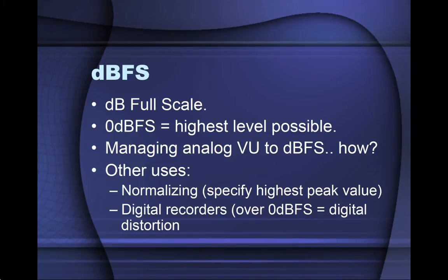Another way of looking at it is, okay, a 16-bit or 32-bit recorder, however many bits it is, 0 dBFS is filling up all of those bits. So if you're going from an A to D converter, the maximum input voltage in an analog sense equals 0 dBFS. It's the most that it can handle without overloading. So it's kind of the Price is Right of recording levels.